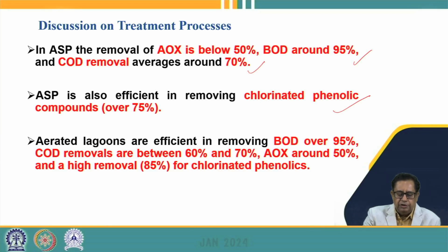So if we talk about the aerated lagoons, they are efficient in removal of BOD, nearly 95%, COD removal is 60 to 70% only, the AOX removal is 50%, and a very high removal of the chlorinated phenols, that is nearly 85%, has been reported for the aerated lagoons.